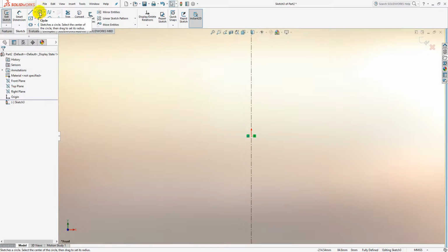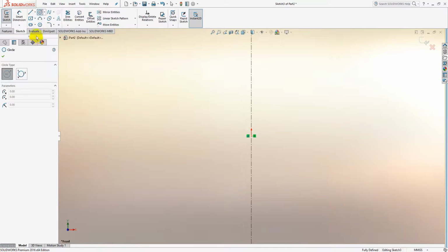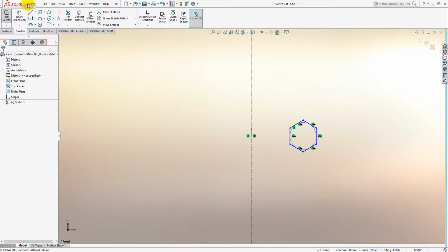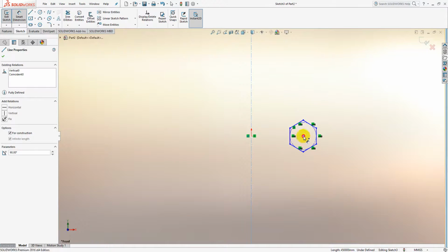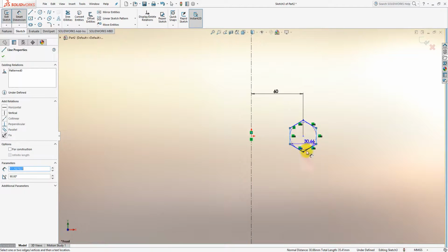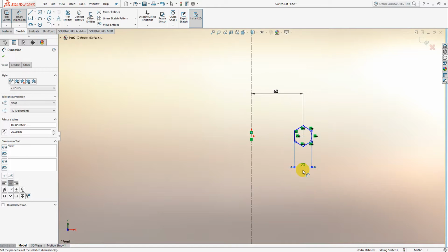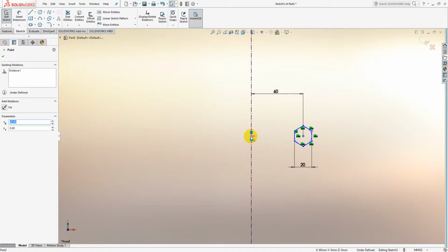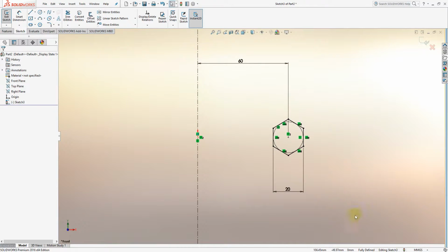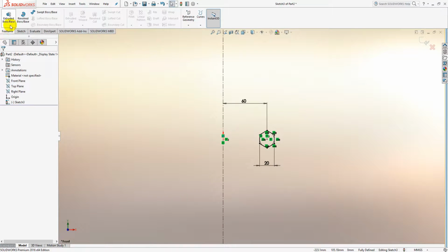And then I'm going to put a circular cross section. No, let's have a polygon cross section. So I'm going to sketch a polygon out at a distance away from the center line. Put some dimensions on that. Make sure that that's fully defined. And there you go. All the sketch entities have turned black. We've got fully defined in the box down at the bottom here, so we can use that for a feature.